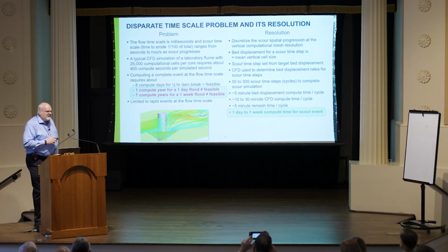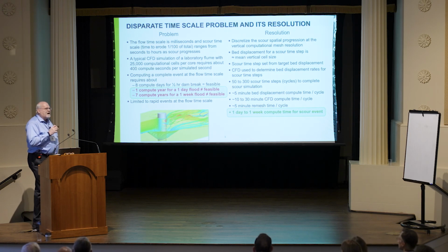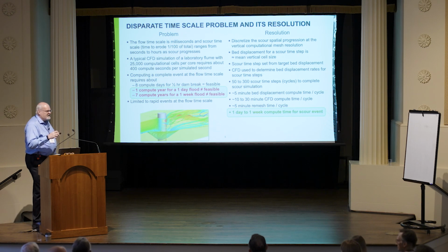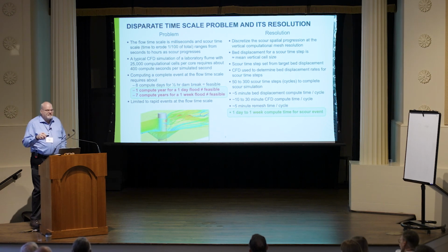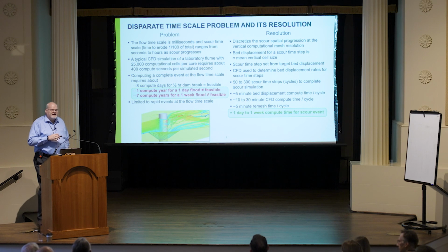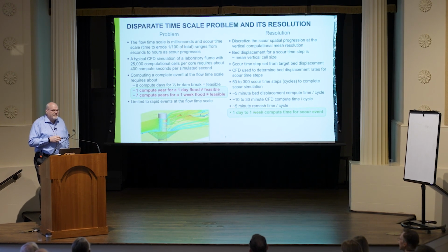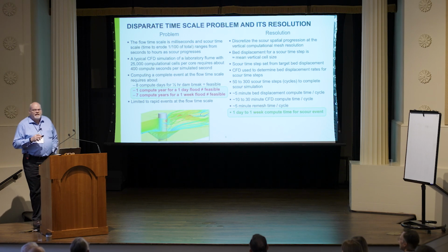So we came up with an idea over the years where we separate the flow calculation from the erosion calculation, so they both run on a different time scale, and that way we can pack that easily into a runtime of, let's say, a day, at the most a week or something like that, on a really powerful computer.